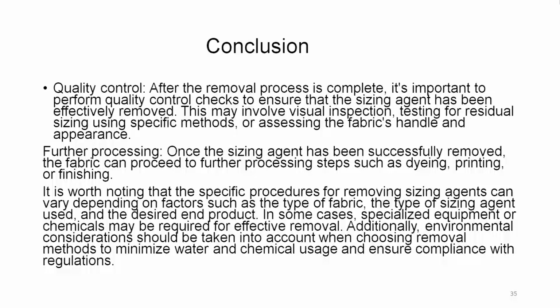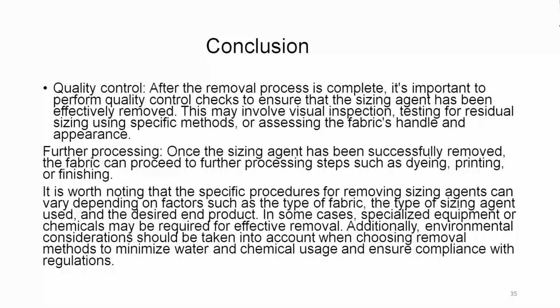So, from this we can say that in this chapter we have learnt that it is worth noting the specific procedure for removing sizing agent, first applying and then removing, because application is required to carry out the weaving process. Then that stiffness is not required any longer for dyeing and printing. So, it has to be removed. Removal, or desizing, is equally important, and both of them generate a lot of effluent. These processes are water intensive, and we also saw that if we use cold water for desizing, it requires larger volumes of water, whereas if we use hot water, it will require less water.